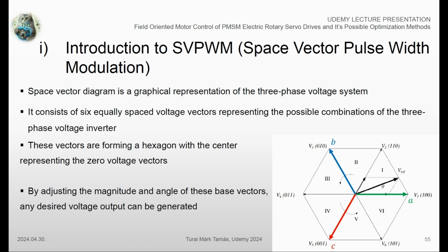The general idea behind the inverters is that we define a high-frequency carrier signal, usually between 10 kHz and 20 kHz in case of PMSM motors, and we constantly change which IGBT shall turn on or off in order to receive the desired reference voltage vector as an output on the inverter terminals.